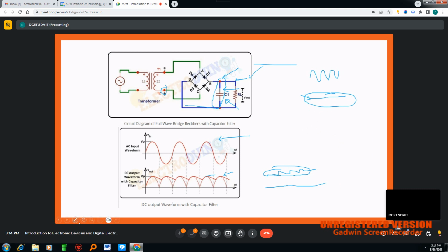When you take a rectifier circuit, you understood that if I want to convert AC to DC, a rectifier circuit is required. The main purpose of the rectifier circuit is that all electronic appliances work with a DC power supply. Another thing I explained with the bridge rectifier: in a bridge, I'm using 4 diodes as switches. During forward bias, the positive cycle, some diodes act in on condition. During the negative cycle, some other diodes act in on condition.